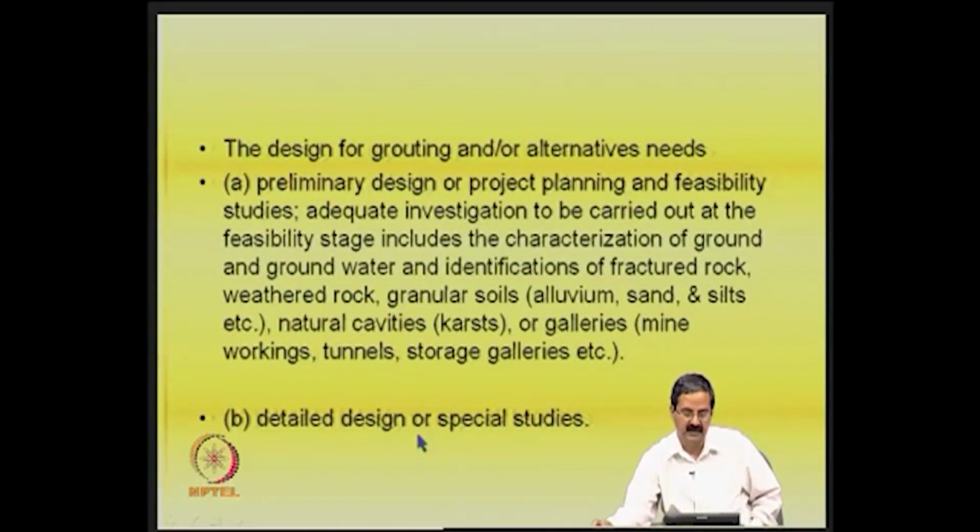So, the design has to be somewhat more careful, because you need to have all this basic information. Essentially the design consists of what type of material you choose as a grout, what the spacing should be, what the pressure should be. There are many methods of grouting.